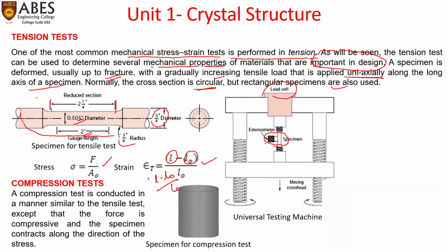Similarly, a compression test is conducted in a manner similar to the tensile test, except that the force is compressive and the specimen contracts along the direction of the stress. So both are similar, just the direction of the applied force is reversed. Other parameters are the same.